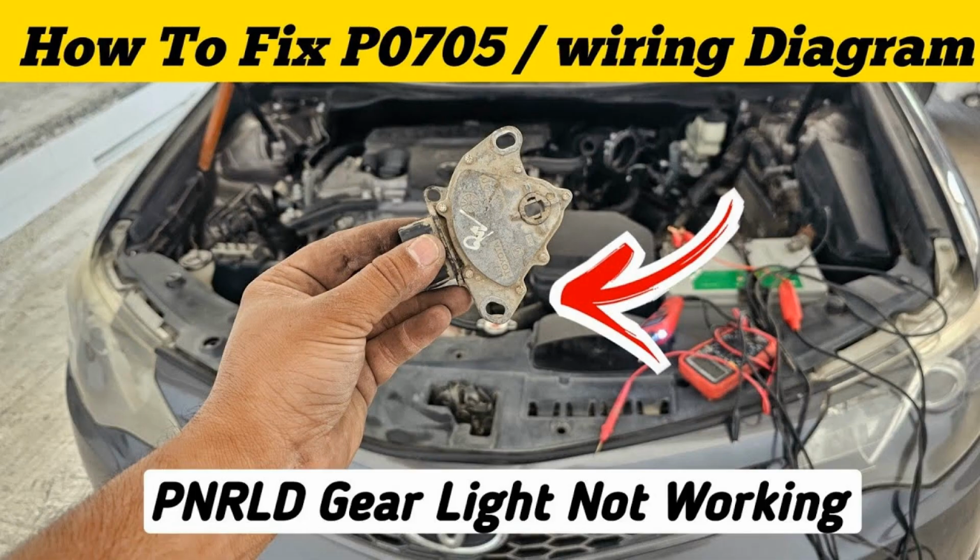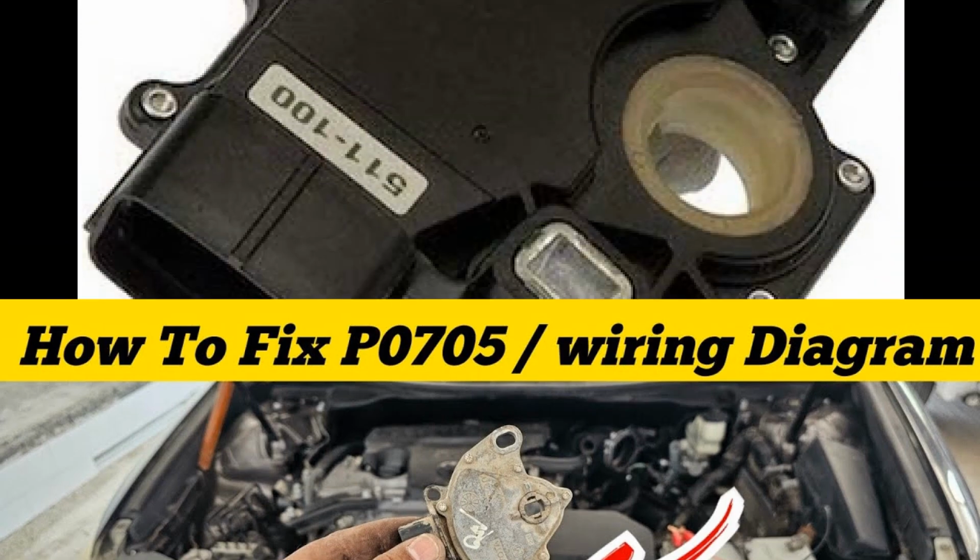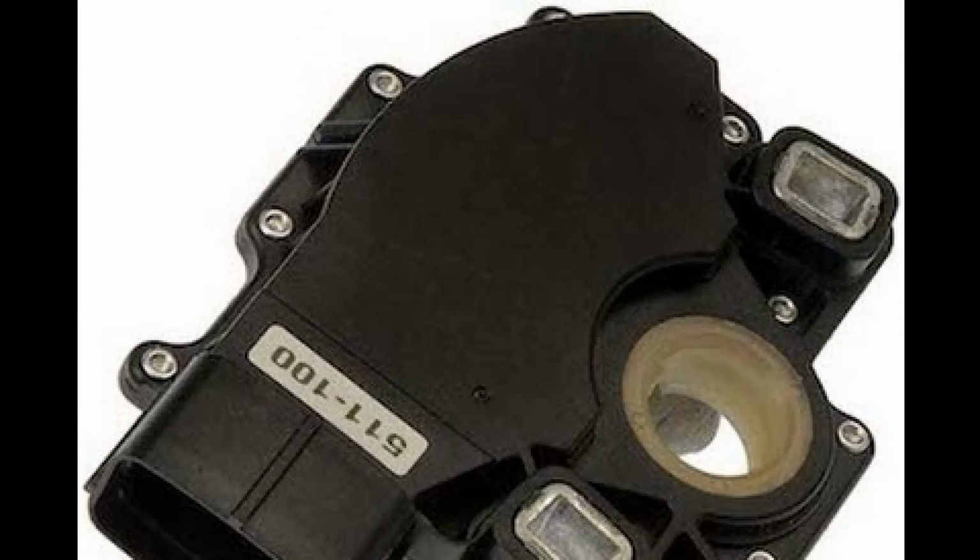Failure of the TR sensor is common with age and high mileage. It is susceptible to weathering. Like any printed circuit board, it is subject to corrosion over time. The good news is that they don't require expensive repairs and are easy to replace with a little car repair experience. Modern models with a transmission range sensor housed in the valve body have a different design. The range sensor is separate from the neutral safety switch and the reverse gear switch. The function remains the same, but replacement has become more serious in terms of both complexity and cost. The easiest way to determine which type is used in your car is to find the part on your local car parts website.